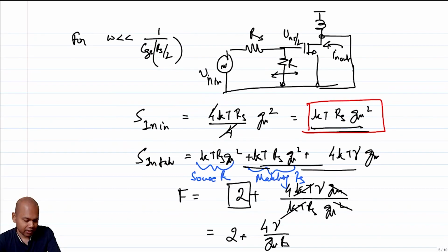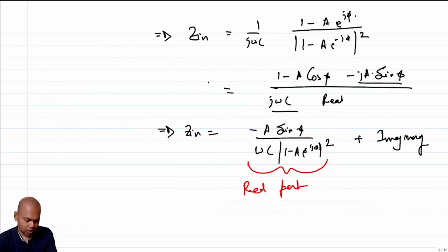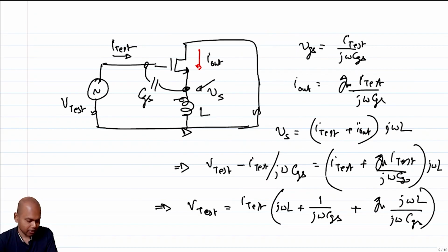So then we were looking for a way of figuring out if we can actually put something to good use, which is not noisy but can give us matching. Then we saw a way, probably if we use these capacitors and inductors in a certain way, and wrap them across some sort of LTI network which has some phase lag, then there is a chance that the input impedance looking into one of the ports will have a real part, and lo and behold, we found a way of going about doing it.